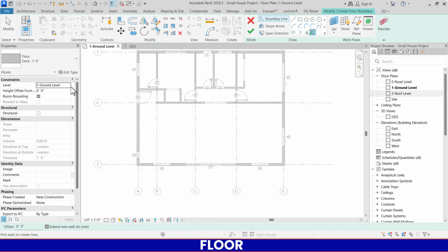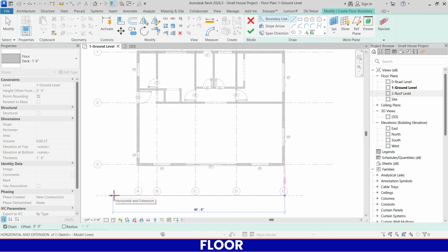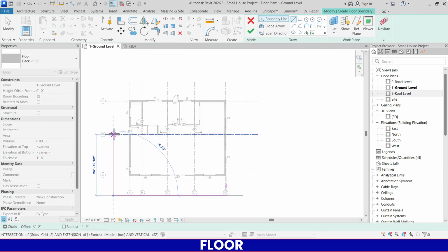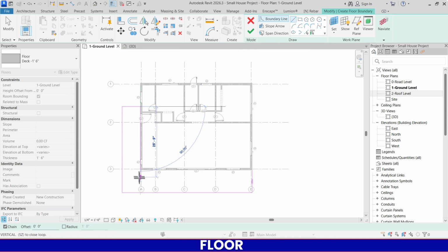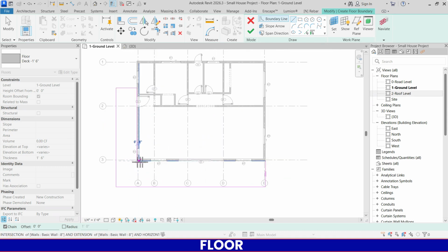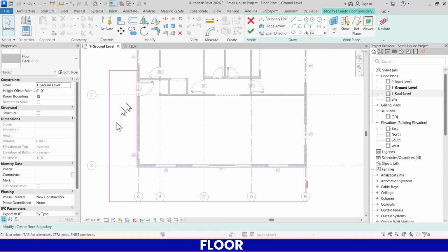And then we will draw where it is required on the ground floor, right, and select the line, and from here add 8 feet, and from here 46 feet, go to maybe 30 feet 6 inches, then here, and then close. Remember, it's very important to close the loop. It should be a closed area, so there would be no error in your drawing.